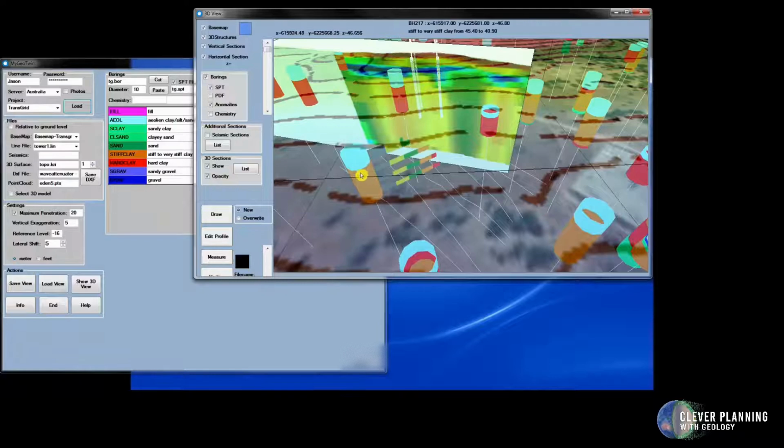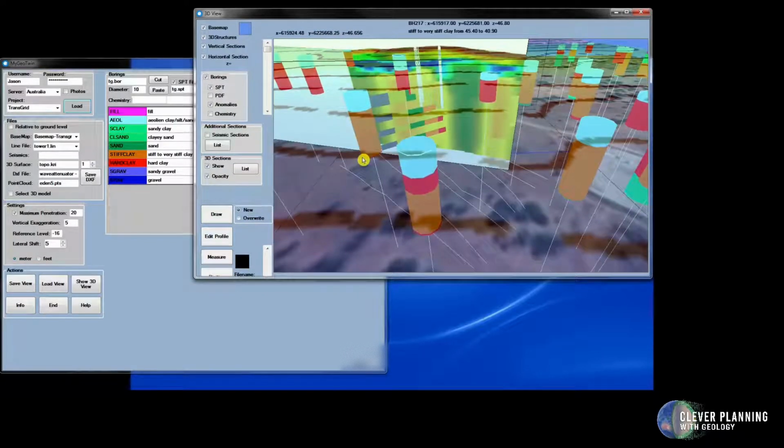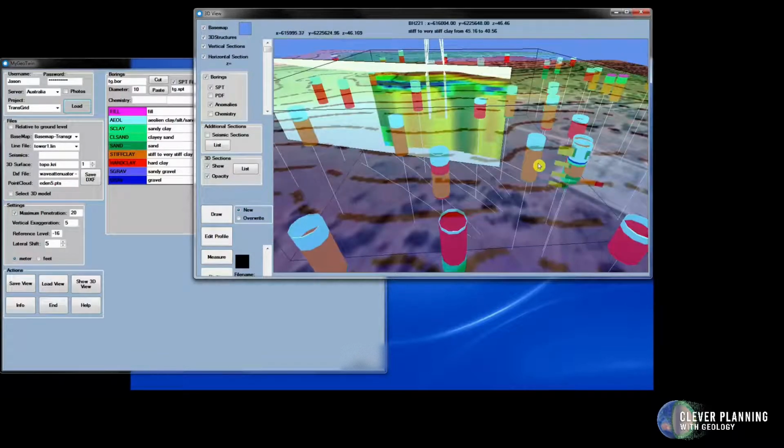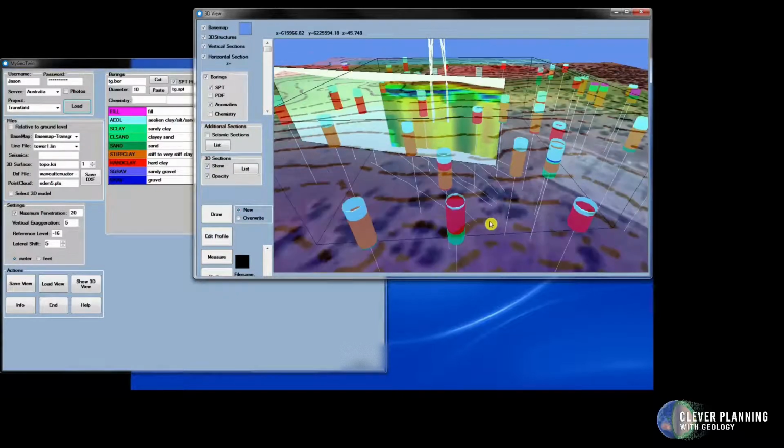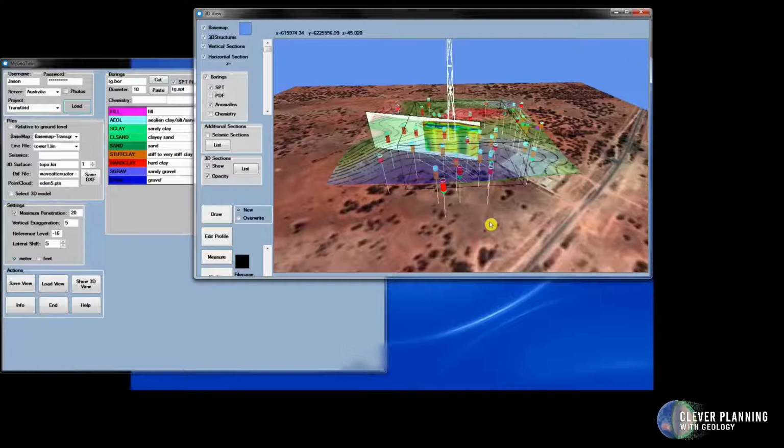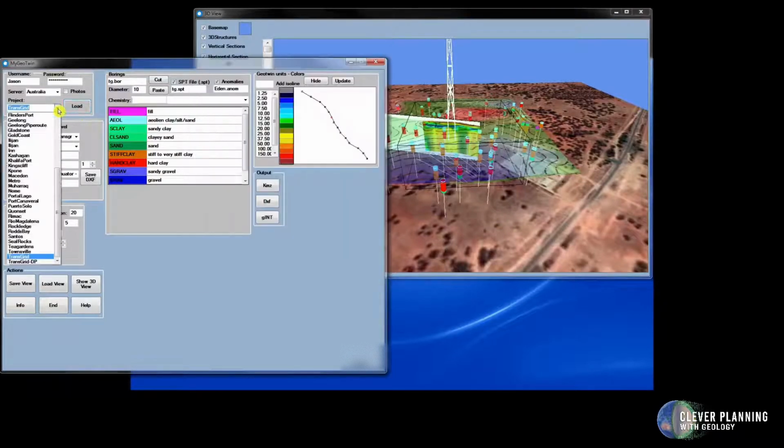This blue layer represents a salt deposit deposited by groundwater movements, but this layer is key to safely earthing the proposed transmission tower, so is critical knowledge to the owner. This example highlights beautifully the importance of always getting advanced digital geophysics first and targeting boreholes both vertically and horizontally.